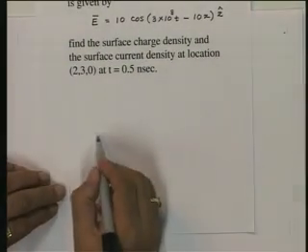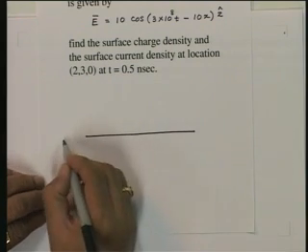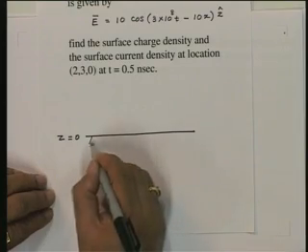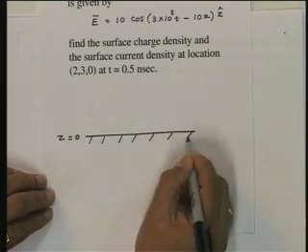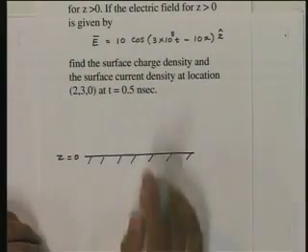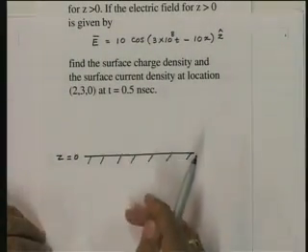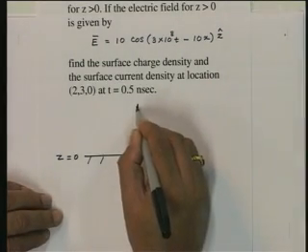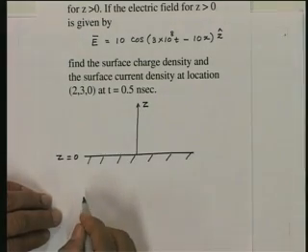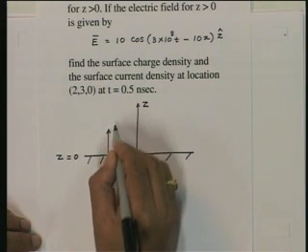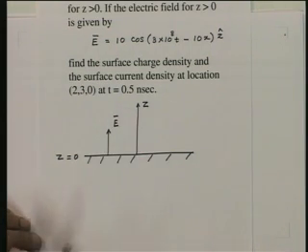So, here the situation is as follows. You are having a medium. So, this is z equal to 0. Below this we are having the infinite conductivity, and since we are now considering the time varying fields, the electric or magnetic field cannot exist inside a conducting medium. So, the electric fields are identically 0 in this medium. Then the z direction is given by that. So, the electric field is normal to the surface. So, this is the way the electric field will be oriented in the z direction.